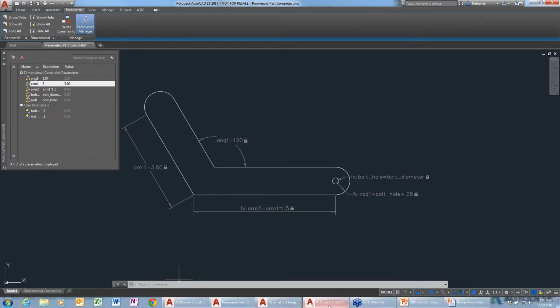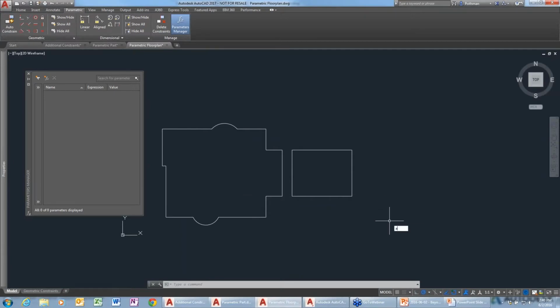All right, so let's jump back to AutoCAD. I don't really know what the answer is, so let's just give it a try. So let's use smooth, and we'll grab these. So at least one has to be a spline, I guess. Okay, so you can't do it just between two arcs. One object at least has to be a spline in order for the smooth to work.